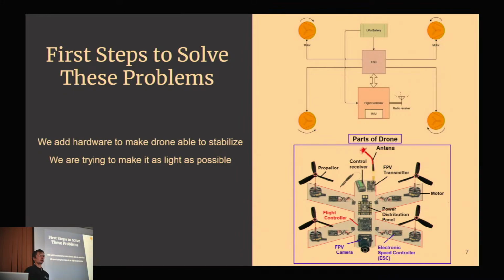But that's not enough for stabilizing our drone. Like I said, the reaction time of a human is not enough at all. So that's why we need the small black box in the middle, which is the flight controller. That's basically a small PCB board with IMUs, gyros, and default parameters. And of course, I didn't mention the MCU for computing and controlling the input from the gyroscope.